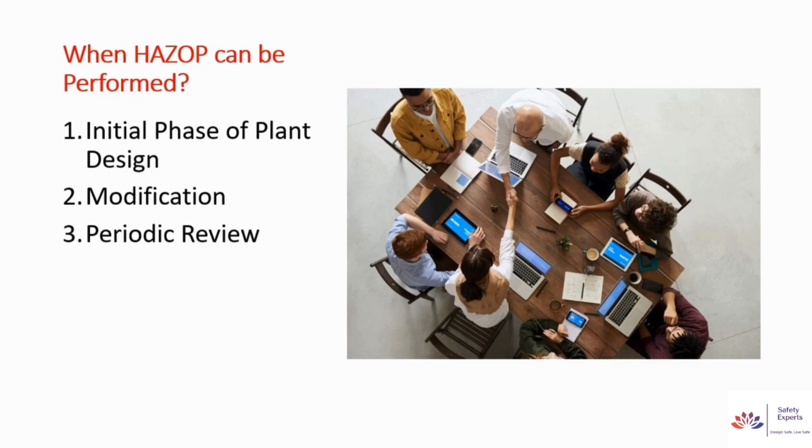And Hazop should not end at one time. It should be periodically reviewed. Best practice is to do Hazop every 5 years, because there is always advancement of technology. There will be lots of upgradation in terms of instruments or equipment, and there can be issues that can be uncovered at a later stage only.